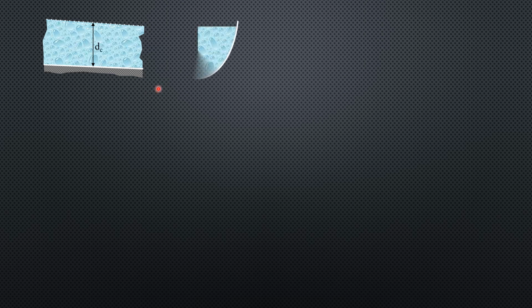So moving on. If this is the side of the channel, the depth of flow is critical. And let's have the cross-section of the channel. We consider a strip on top where the top width is B and the differential depth is dD. So that's the differential area, B times dD. The cross-sectional area is denoted by A. So this blue strip here is the differential area, which is equal to top width times differential depth. Because at that level, the velocity is the same at all points on the surface.